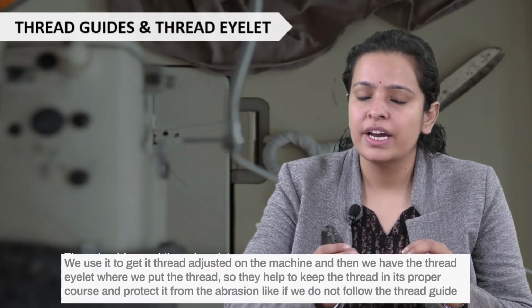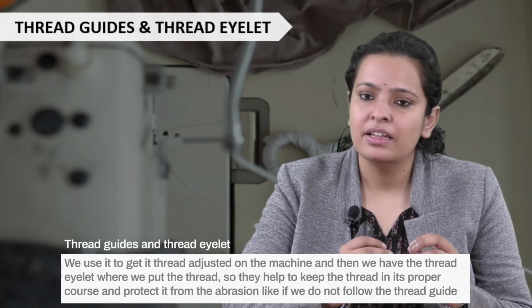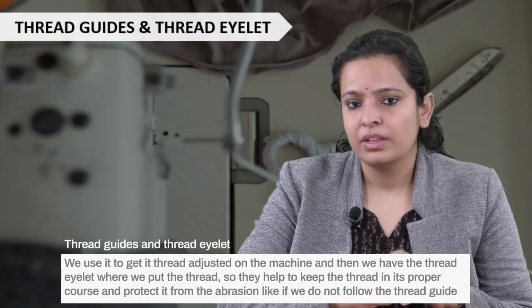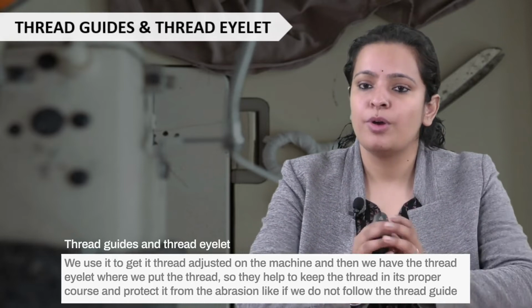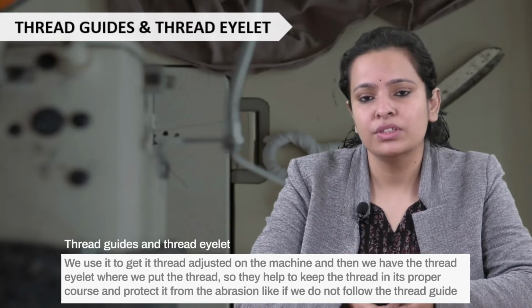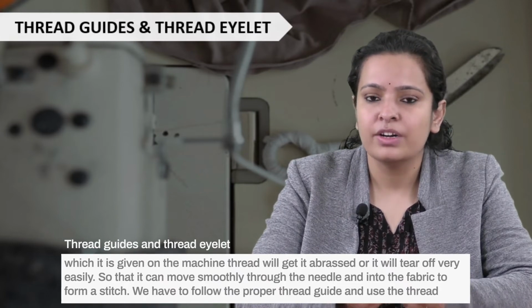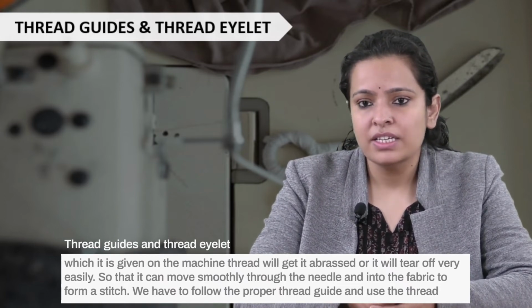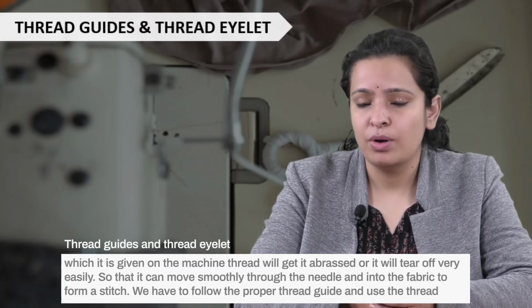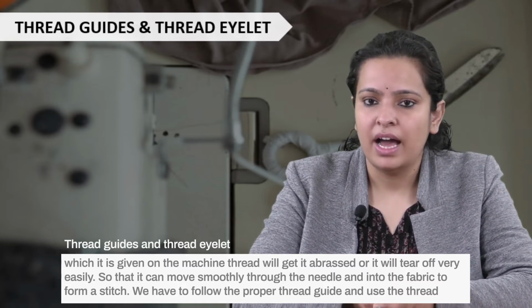We use it to get the thread adjusted on the machine, and then we have the thread eyelet where we put the thread. They help to keep the thread in its proper course and protect it from abrasion. If we do not follow the thread guide given on the machine, the thread will abrade or tear off very easily. So that it can move smoothly through the needle and into the fabric to form a stitch, we have to follow the proper thread guide and use the thread eyelet.